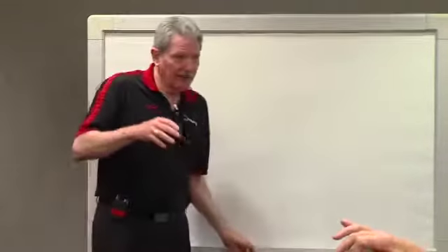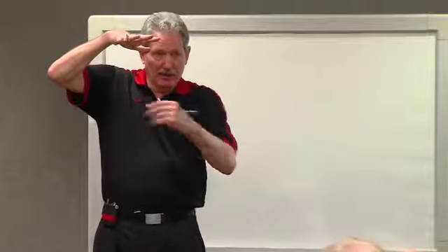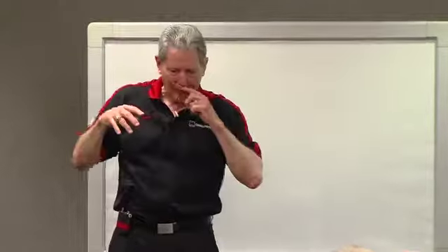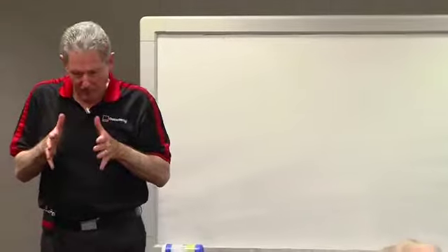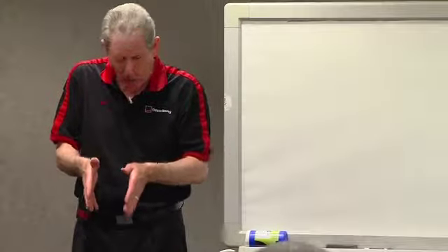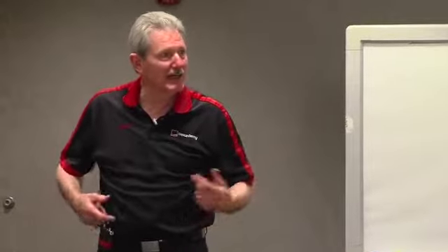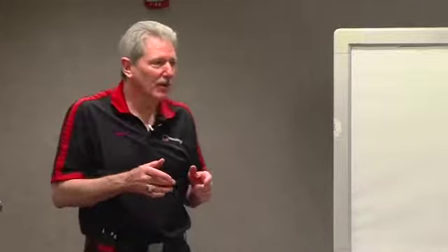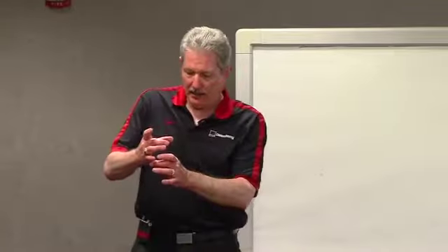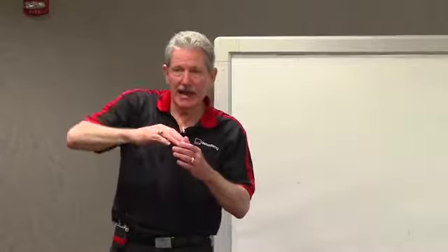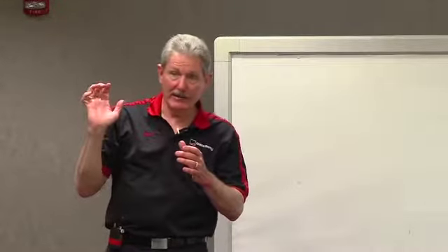I told you about the diode. You build the bias, the dam, the water's got to go over it. On the transistor, every charge carrier that goes into the base carries 10 with it, piggybacks 10. That's how you get the amplification. A MOSFET works entirely different. Say I've got a hose and I've got a valve on that hose and it pinches it. When I apply voltage to the gate, I open that channel. When I take the voltage away, I close it, so I'm blocking it.